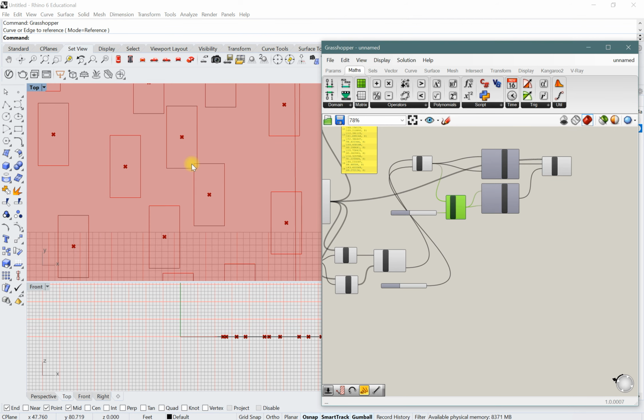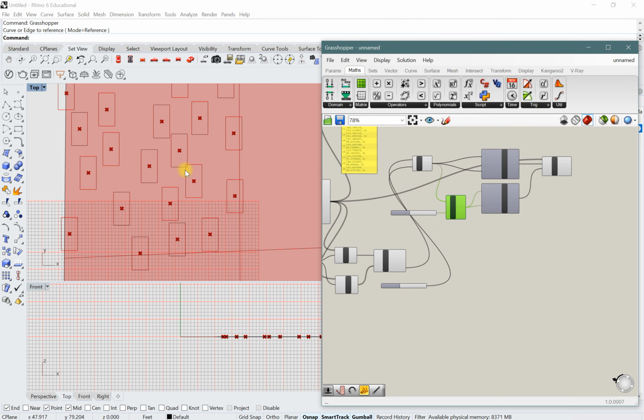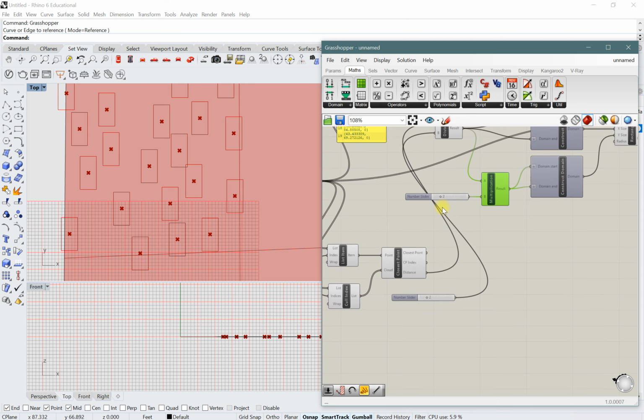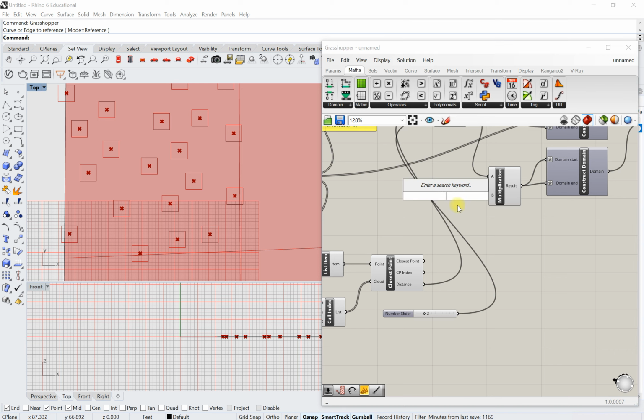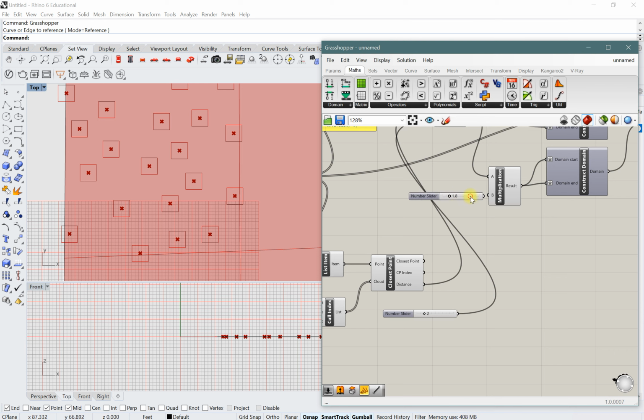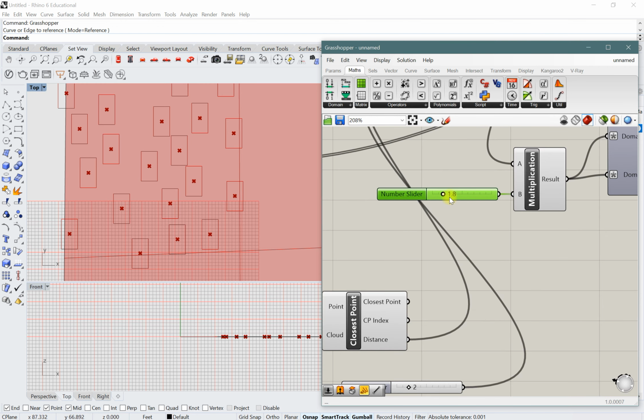You see we're getting a little overlap here. That's okay if that was bothering you, right? We could try lowering this value a little bit. I'm going to type 1.8. And if you type a number with a decimal, it'll give you what's called a floating point slider that you'll notice instead of just jumping from 1 to 2 to 3, it gives you the points between.